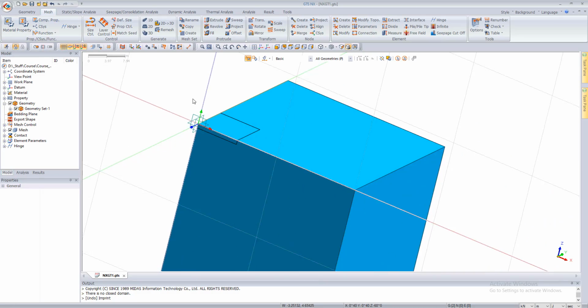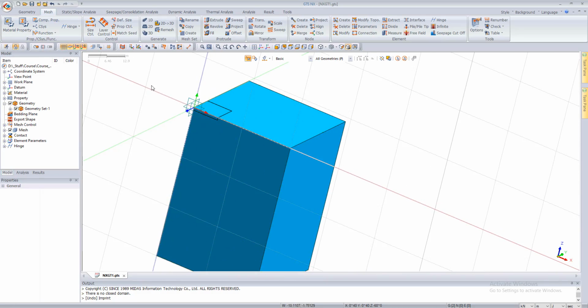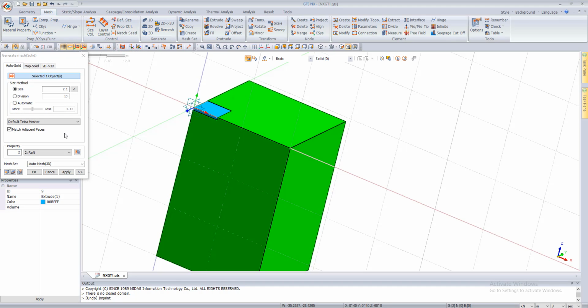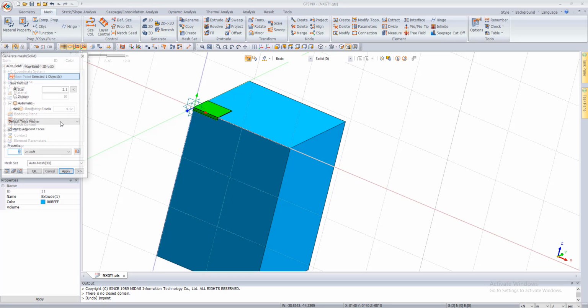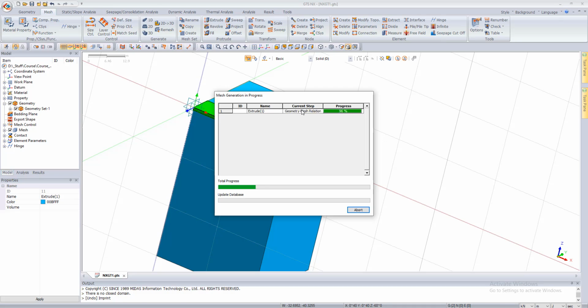Now we have already created our problem. Now it's so easy to create a mesh from the 3D mesh. I create this hybrid and I call it soil. I prefer to mesh my raft first, and I will mesh it to 0.25. We can mesh it to 0.5, it's totally fine, and we call it raft, and we say apply.